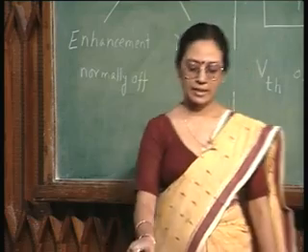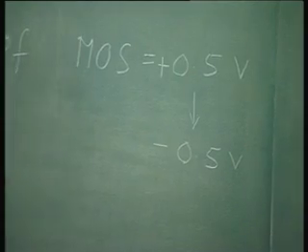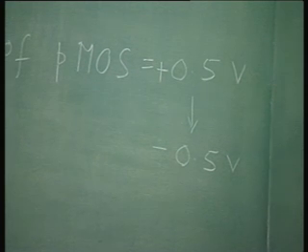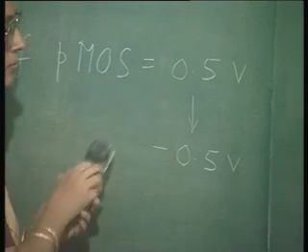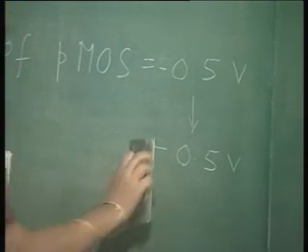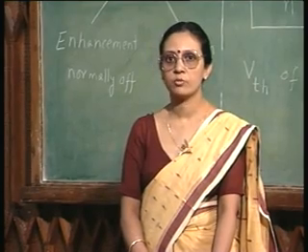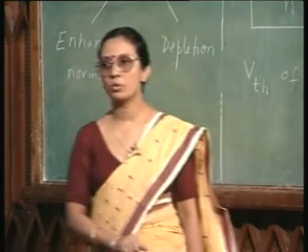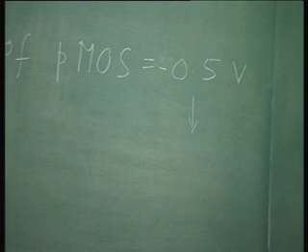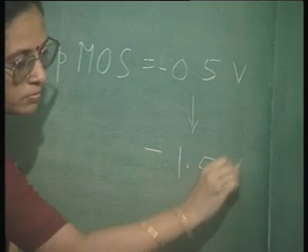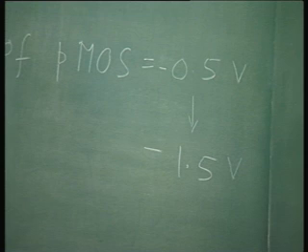In contrast, let us think about the threshold voltage of a P MOSFET, ideal hypothetical enhancement mode P MOSFET. It should have a negative threshold voltage. And again, as before, I have a large density of positive charges in the oxide, and therefore, the threshold voltage got shifted more towards the negative direction, by the same amount, minus 1 volt.